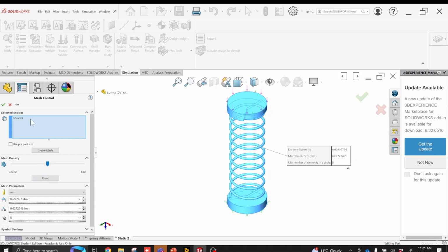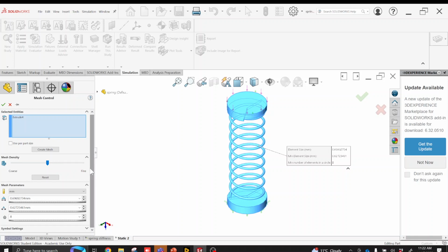You could just leave it in the middle to start out with, but you can control the mesh density however you like. The density of the mesh kind of dictates how many individual calculation points there will be. So if you have very sharp geometry that you want to properly resolve, that's a good place to refine the mesh. You can just globally refine it by dragging this to coarse versus fine. Finer meshes will have higher density, coarser meshes will have less density,